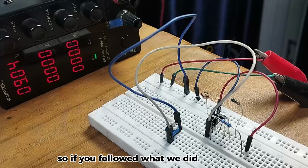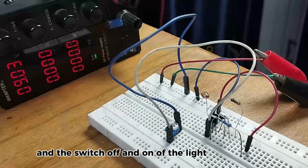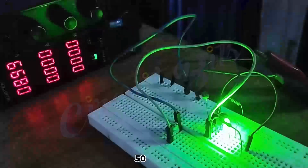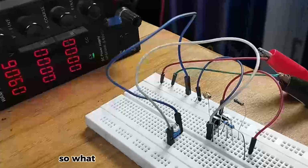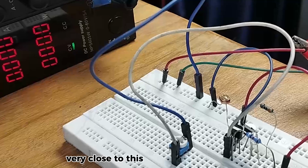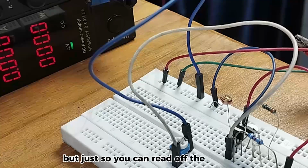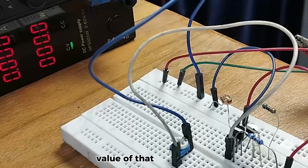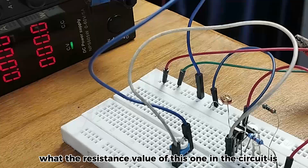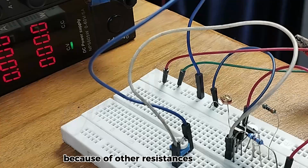So if you followed what we did meticulously, you should have this, and the switching off and on of the light should happen at about 550k ohms. So what you can do is put another LDR very close to this one on the breadboard, not connected to the circuit, but just so you can read off the resistance value of that particular one to know exactly what the resistance value of this one in the circuit is. Because if you read this one while it's in the circuit, you might have a wrong reading because of other resistances in the circuit.